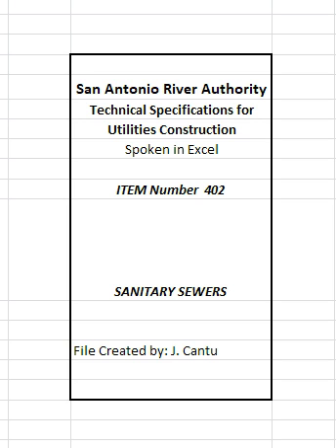Pipe shall be cut from measurements taken at the site and not from the plans. Necessary provisions shall be taken in laying pipe to provide for expansion and contraction. 5. Ductile iron pipe. Under no circumstances shall ductile iron pipe be cut or repaired using an acetylene torch. Cuts and repairs must be made by a cutting machine which shall be approved by the engineer. 6. Trench safety. All excavation and trenching shall conform to item number 700, Trench Excavation Protection.